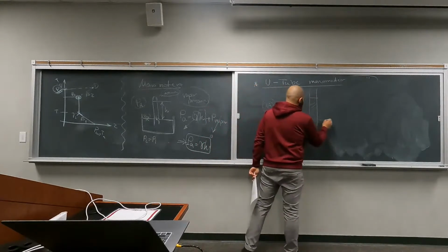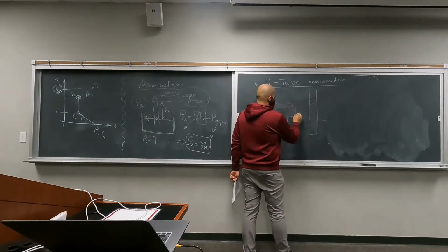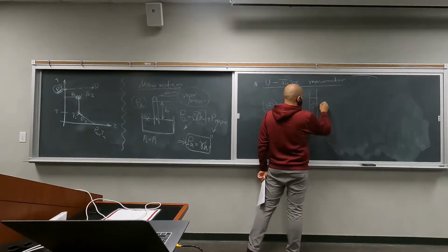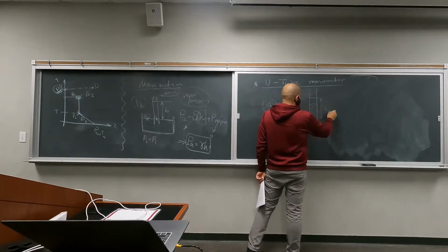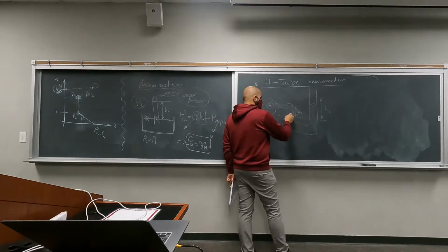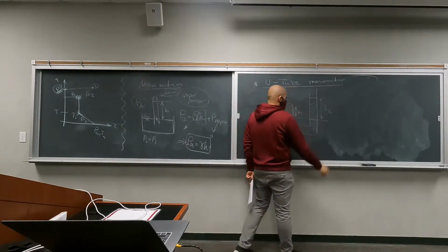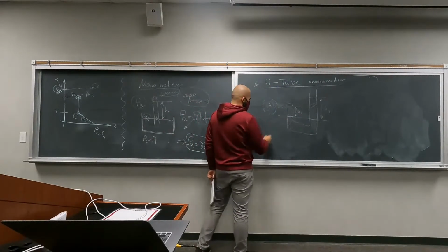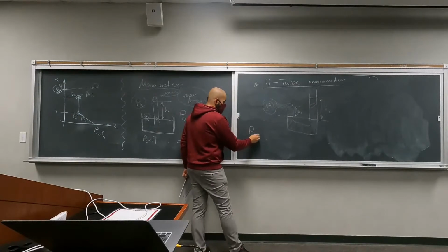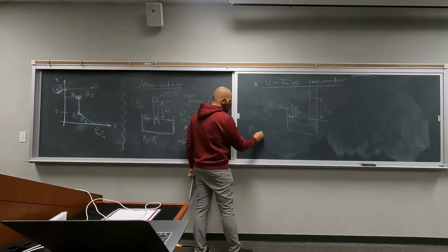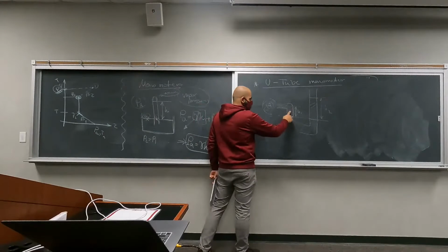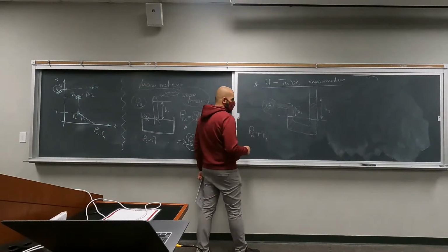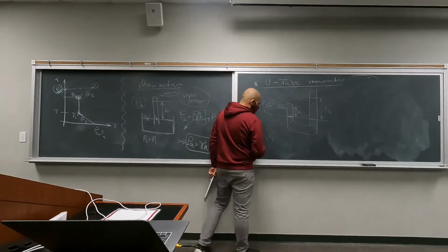And we know the height from this location and this location. So we have a base location. The idea is the pressure at these two base locations are the same. And the pressure at this base location is the pressure inside this, whatever that is, P of A plus gamma of, let's call it liquid 1, gamma 1 multiplied by H1.